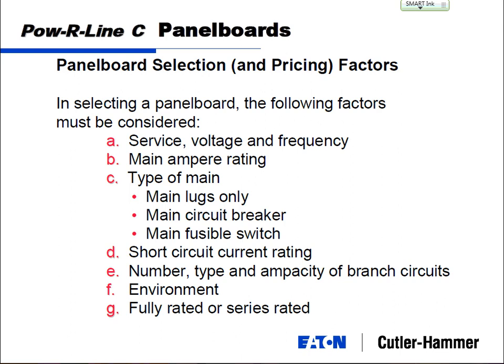You guys have heard the NEMA classifications for enclosure environments? The standard that we say is NEMA 1. That means it's not really protected from any environment. You're just enclosed for safety. NEMA 12 is another option that adds dust proofing, so maybe that's a strip of gasketing around the trim.